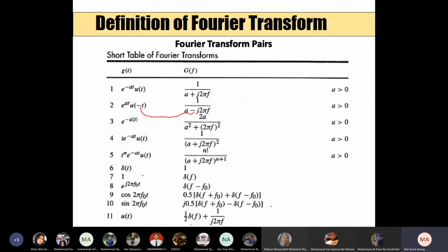This is actually the impulse. An impulse in the time domain, in the frequency domain is equal to 1. If it's an impulse in the frequency domain, in the time domain it is equal to 1. So DC will give this. This is actually 1 from minus infinity to infinity, so it's a flat line. So in the frequency domain it is an impulse.